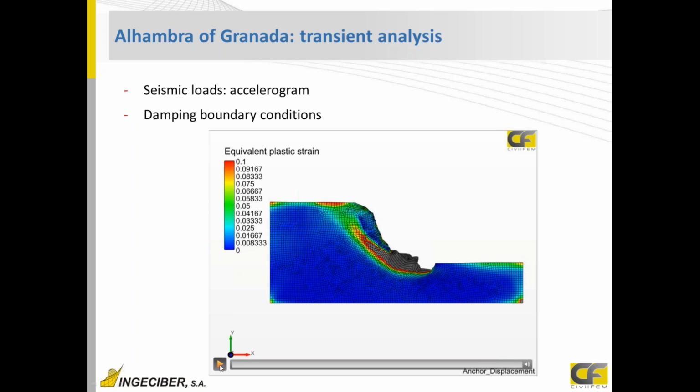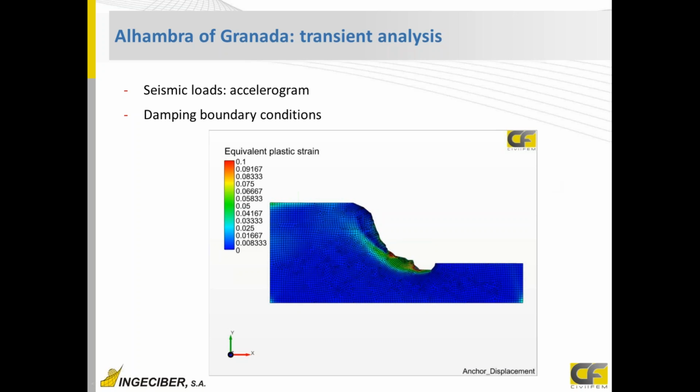We can see here, if we repeat the video, that when applying the accelerogram, the yielding zones start happening. This is the first anchor configuration, where the yielding surfaces happened and didn't improve the slope much. When we applied this accelerogram to the slope without the anchors, the model didn't converge because instability happened, and with all the anchors we obtained practically no yielding. So this one, with the second configuration, has equilibrium, but a lot of yielding zones and sliding surfaces.